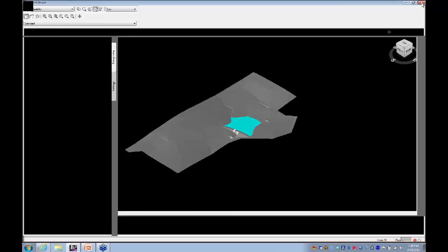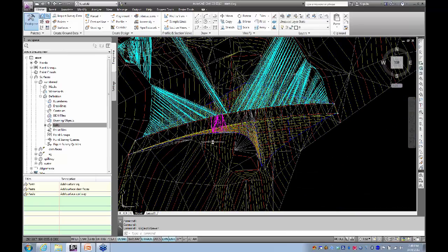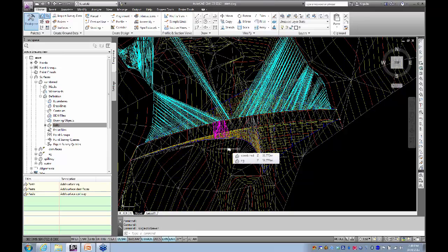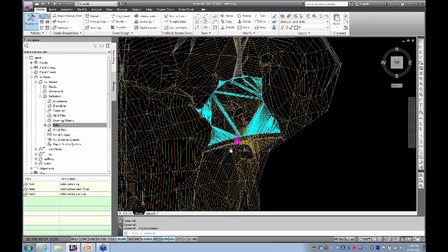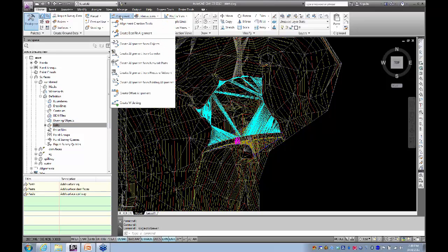Alright. Trick for young players, and old players too from time to time, is that interaction I was talking about between objects that are in the same container or site. So let's say, well, let me make an alignment, because alignments can be part of a site, and this is why you would normally keep alignments out of all the sites.